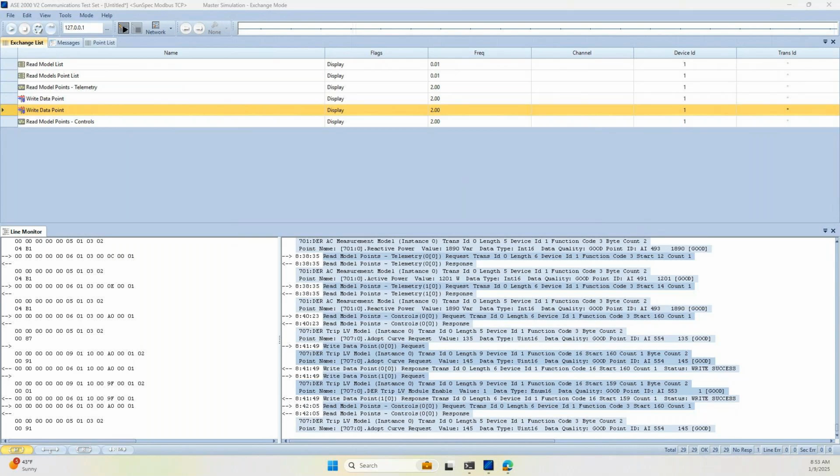And the next question mentioned is: what is the maximum number of MFMs in one SunSpec Modbus link? I'm not a protocol expert, but I assume multiple device IDs can be specified under one Modbus port. That means you'll have a TCP port or serial port, and under that, like DNP3, you can have multiple link addresses and specify multiple devices there.